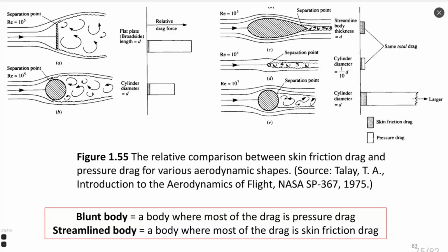So we see different values of drag coefficient. But not just the values are important, also important is the source of this drag. In case of the cylinder, case B, and case A, the flat plate, as you may see on figure 155, we see that drag force is created mostly by pressure. This white zone here is the pressure influence or pressure source.